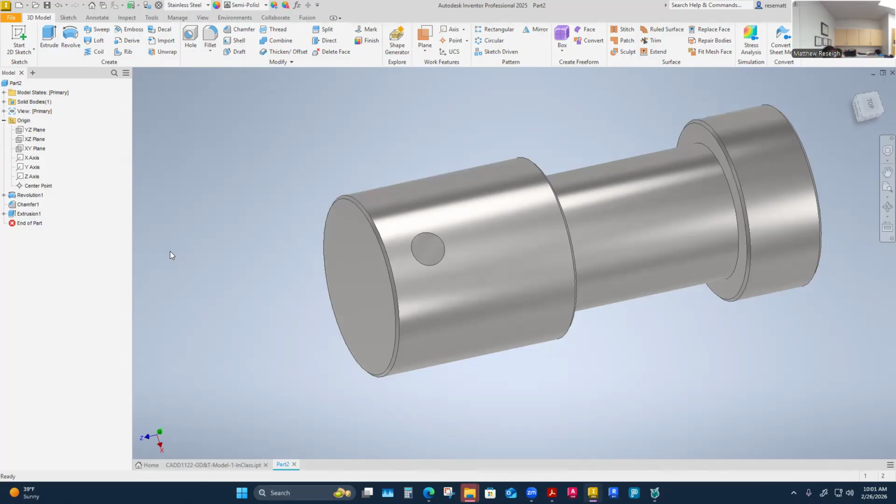If you ever see a 304 stainless, I call it the run-of-the-mill stainless. It's all over food processing, and it's readily available on the shelf. 304 stainless is super common, but it's not the most corrosion resistant, and it's not the most easily machinable type either. There's 303 stainless, which I'm thinking this part could be made out of. I think it has a little more sulfur in it, which makes it easier to machine, but not weldable.